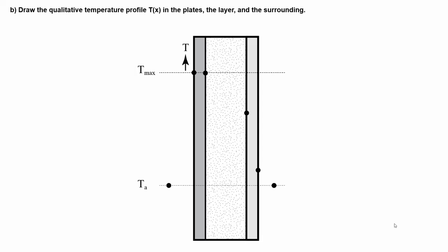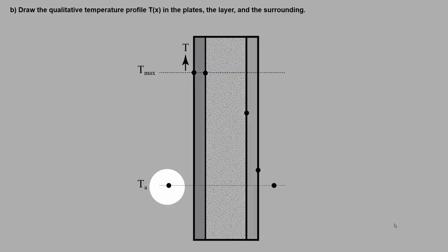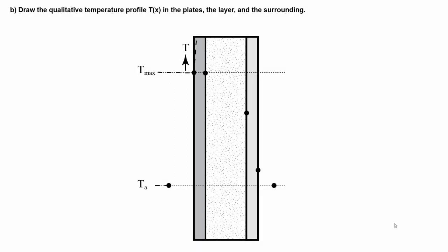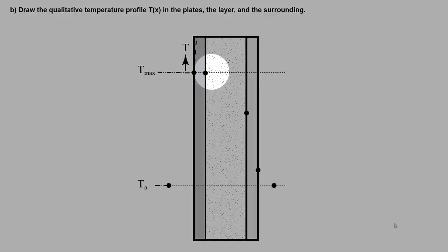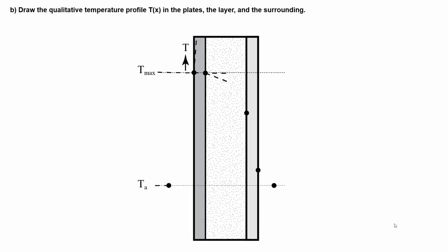In the left layer, the temperature difference is almost negligible, which is often the case for materials with high conductivity such as aluminum. It helps to first draw the slopes of the profile at the different points. For the left side, we know that the slope should be horizontal, which is a characteristic for profiles in fluids where convection is happening. At the interface between the solid and the fluid will have the steepest slope, as in general those have lower thermal conductivities than solids. At the interface between the two solids, the left layer its slope will be less steep due to its higher thermal conductivity.